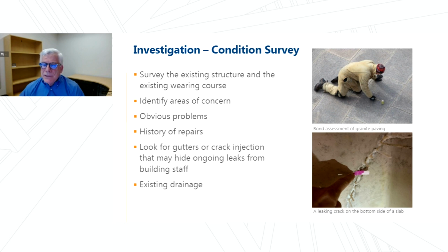Try to understand the vintage of repairs and also what types of repairs have been done in the past. Look for gutters, crack injection, things of that nature. What's the existing drainage system?